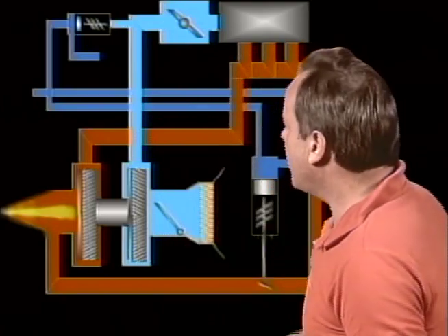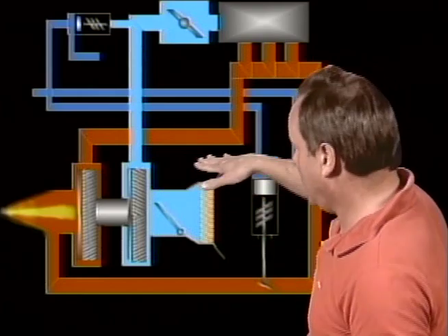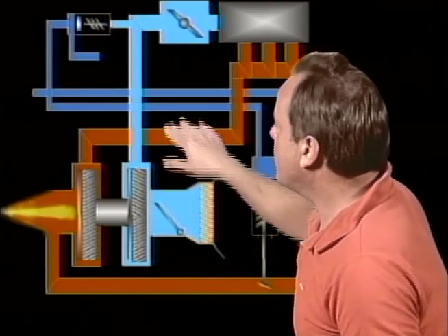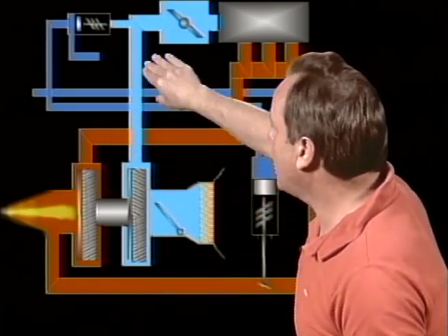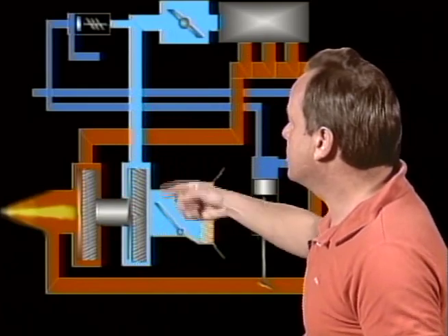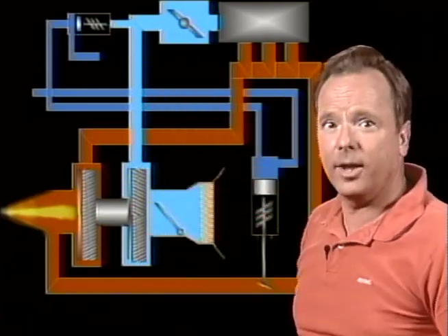And the reason for that is the turbocharger will start working real hard when the airplane has reached its critical altitude. Ambient air pressure drops off, and it's much, much less. And the pressure ratio controller limits how much ratio of boost. We'll say a 2 to 1 boost is all it will allow over ambient, and it limits that so that you're not overheating the turbocharger and having too hot air going into the engine.